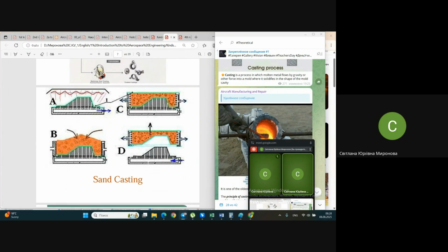That is why casting has usually been used for manufacturing parts which are not of high quality in sizes and surfaces, but of complex shapes. Whatever this complex shape is, it may be repeated by the casting process with a very high level of repeatability, but the accuracy of sizes will not be good. Accuracy, actually, not tolerance. Tolerance is our demand on accuracy.